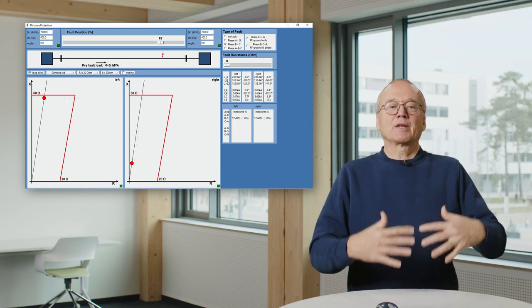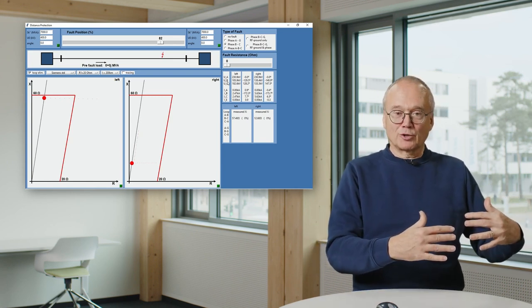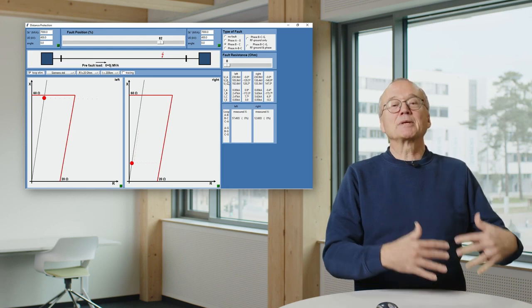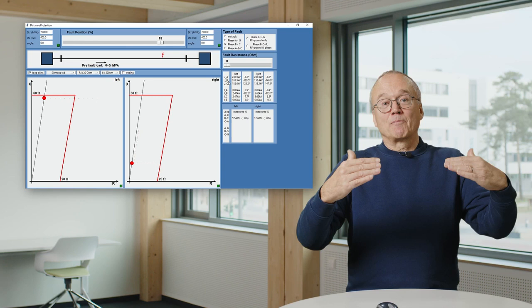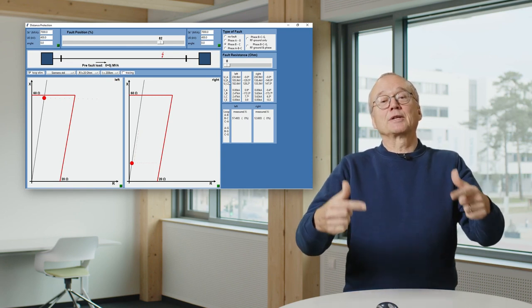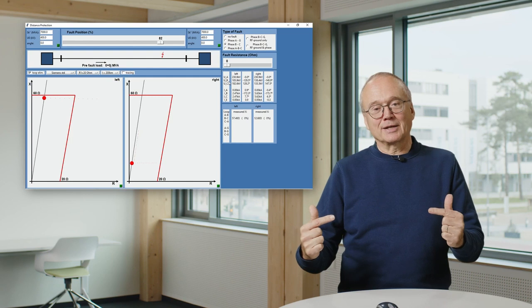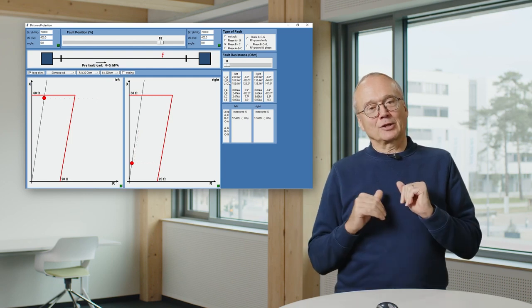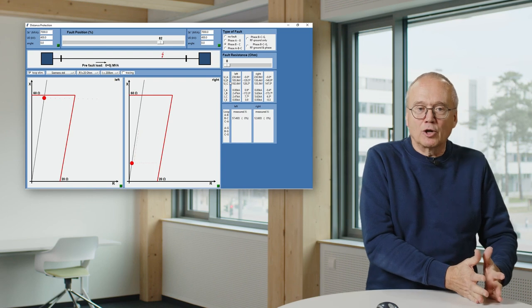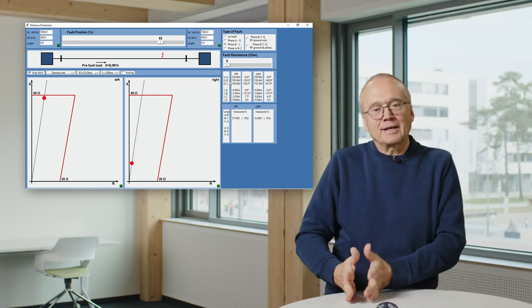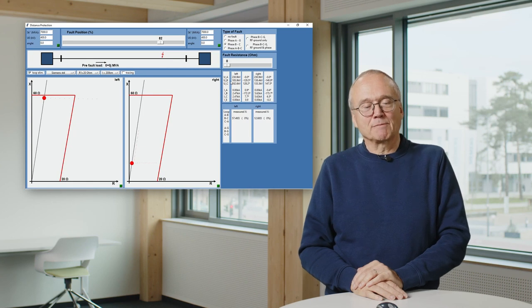And that means if we have a power flow on the line before the short circuit occurs, the voltage phase angles are different. If the voltage phase angles are different, during the short circuit the current phase angles are different, and that causes problems. That means there is a relation between pre-fault load flow and the movement of our impedance measurement.